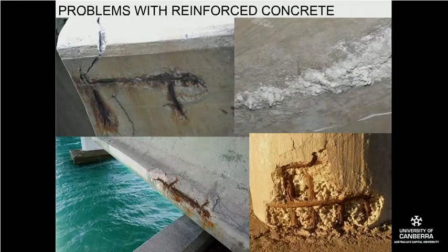This can also occur if you don't allow your concrete to cure properly, which means that if it dries out too fast, you get shrinkage, and if everything shrinks away from one bit, you're going to end up with cracks, and cracks are also where water can get in. Okay, so this is called concrete cancer, but it is repairable.